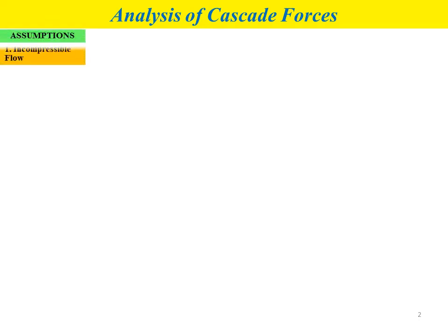Our first assumption is the fluid flow is an incompressible flow, where we will use a low Mach number, which is equal to 0.3, and the compressibility effect is neglected. The second assumption is the fluid flow or the device that we consider in the analysis, we consider as a steady flow process, a steady flow device. By using the second assumption, we can use any simplified thermodynamic equation.